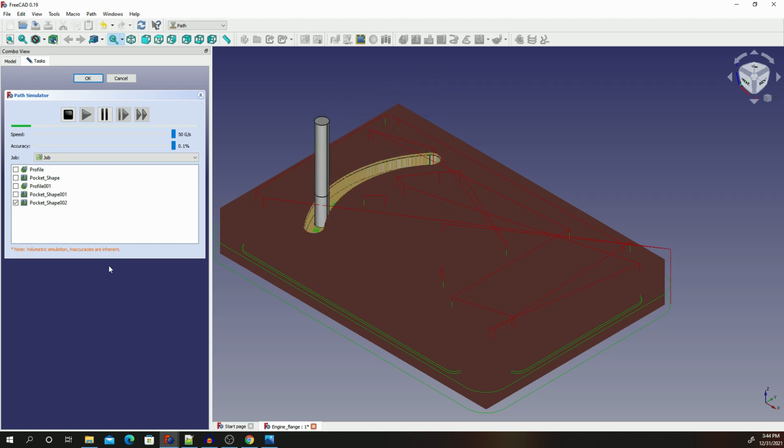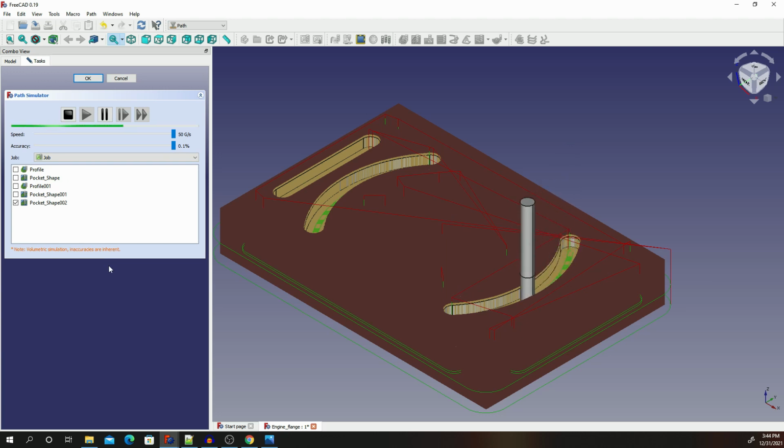Always test to make sure the operations you've applied actually work. And as a step of caution, CNC in FreeCAD is still on an experimental level. So once you simulate this and it works out, I would suggest check the code and compare with the operations on your machine to just make sure the G-code matches the code that your machine is going to use before you actually run this code on your machine.